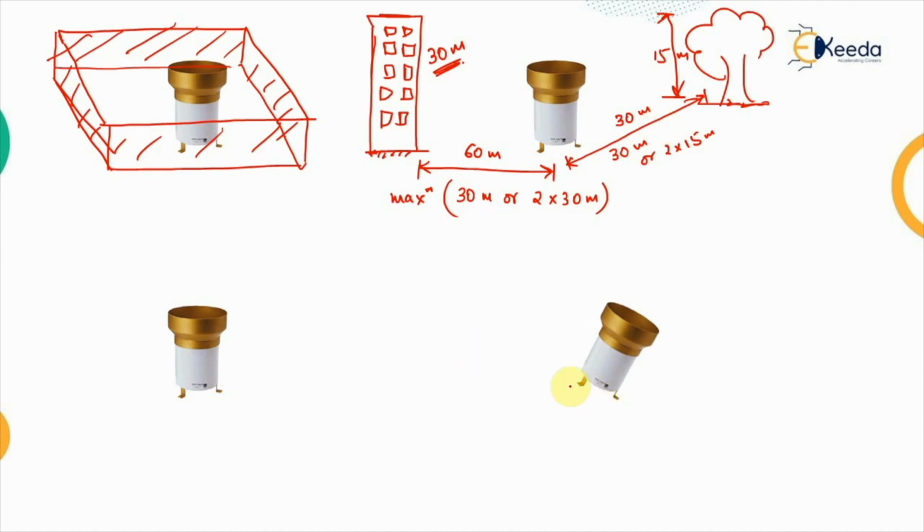The third condition was that a leveled surface should be present below the rain gauge, because if it is inclined, then the water which will be falling into this will correspond to the area which is at an inclination. This is an effective area, while the actual area should be like this. Therefore there will be some abnormalities in the values which we will be getting.